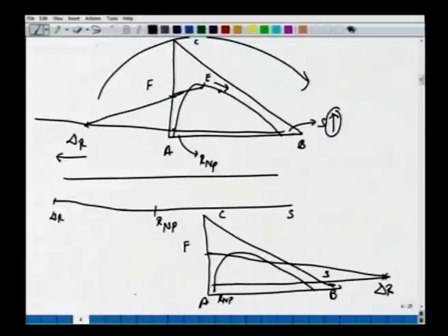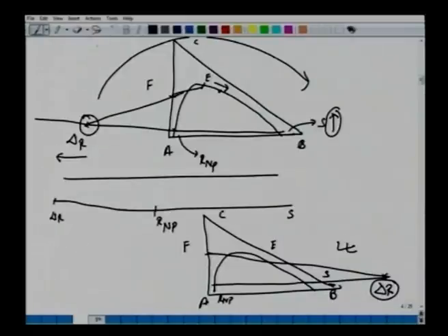So it's very important that we understand the locus of this del R point here. At a certain amount of solvent, if del R is on the left hand side, like in this case here, we increase the amount of solvent till this line becomes parallel to this, right? It keeps on moving in this direction till it becomes parallel to this. We further increase, now the line appears on this right hand side. So we have now this F and A. Now let's see what are the conditions when the operating line becomes parallel to the equilibrium curve.